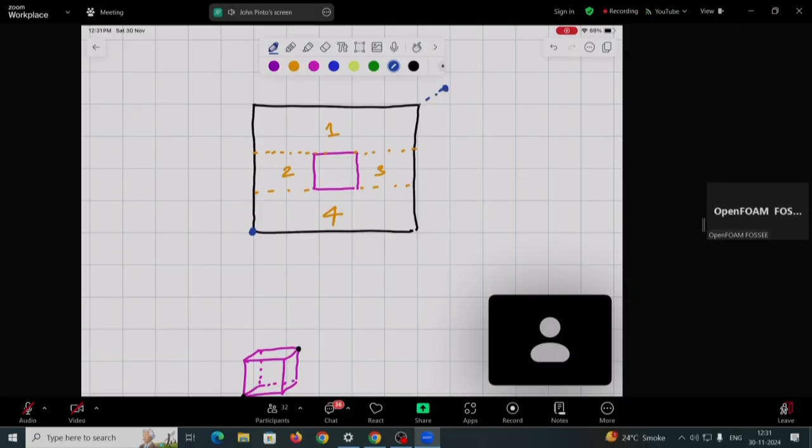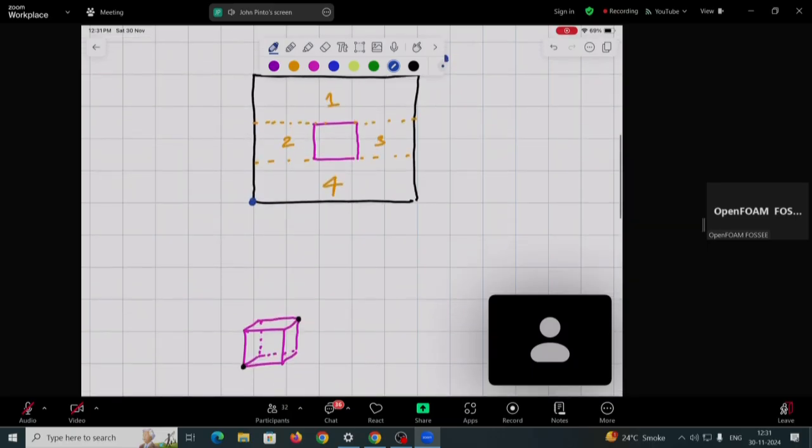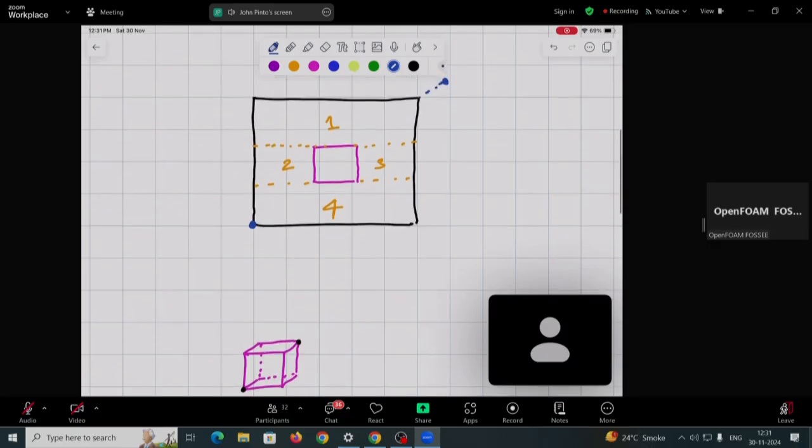And select that. So it will capture all the cells within the black box. Now, once I have captured that, the disadvantage is, remember that all the cells within the black box also lie within the pink box over here. That means within the heater. So all the cells of metal also have the cells of heater within that. So I would have had to capture all the cells within the black box and delete the cells within the heater. So that is another way of creating a cell set for the metal region.